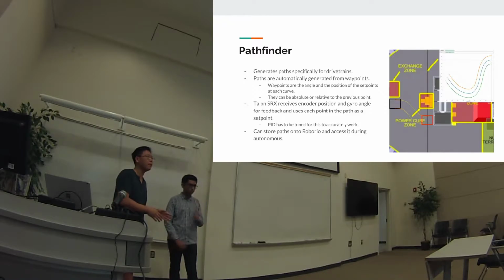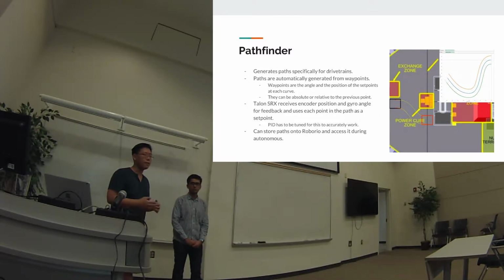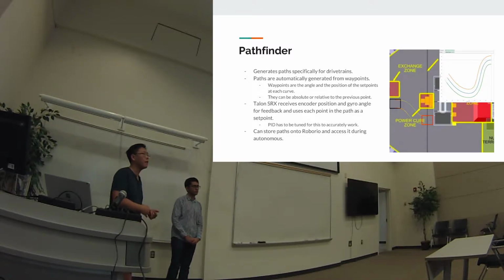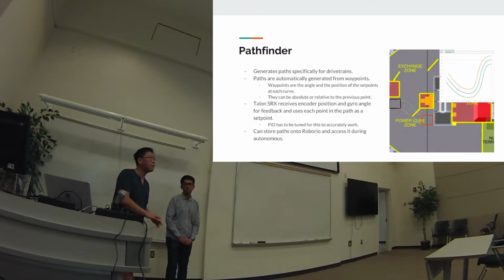It's not motion magic, it's motion profiling. I forget the exact name of the control mode, but that allows you basically to stream motion profiling points or trajectories to the Talon SRX, and the Talon SRX will run the trajectories you're passing. Another thing is the Talon SRX has the sensor input, and that's good for encoders, but I believe the Pigeon IMU, I forgot when that came out, I don't think we had it at that point. So we couldn't connect a gyro to our Talon SRX either.